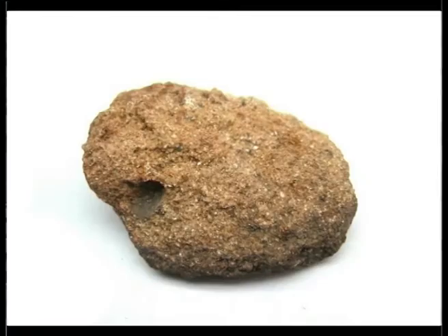Igneous rocks, being crystalline in character, compact and interlocking in texture and uniform in structure, possess very high crushing strengths compared to sedimentary and metamorphic rocks. In the sedimentary and metamorphic rocks, presence of planes of weakness such as bedding planes, foliation, schistosity and cleavages greatly affects the compressive strength both in direction and magnitude.